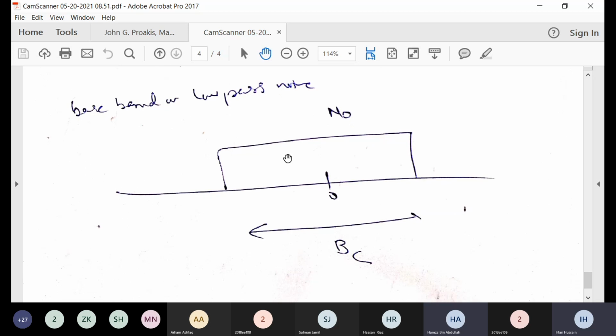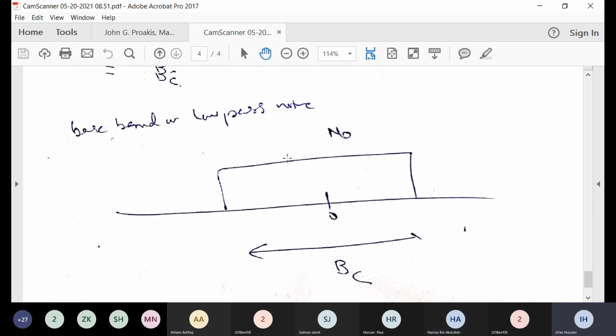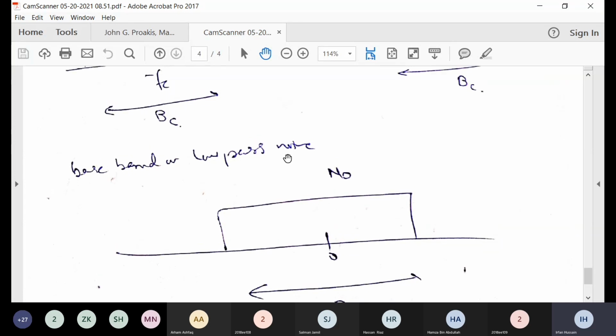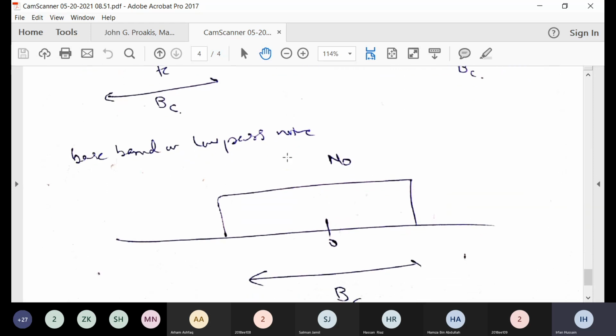ठीक है, लेट्स गो, हम चीज़ों में टाइम ना ज़ाया करें, हमें लेक्चर करना है। So I was trying to explain a very, very important thing, that what is the baseband or low pass noise. So both the quadrature and the in-phase noise are just that you have brought the negative and the positive part of the band pass noise to low pass frequency. That is why its heights become double.